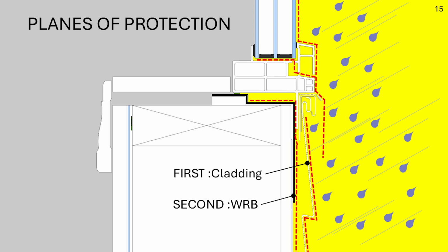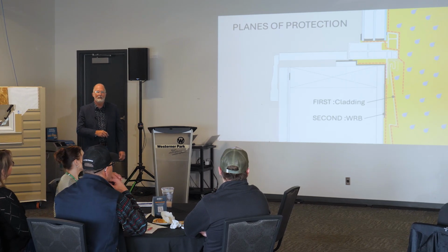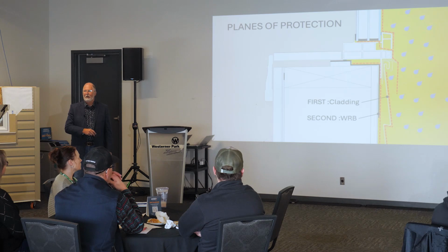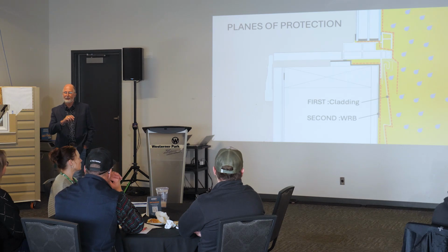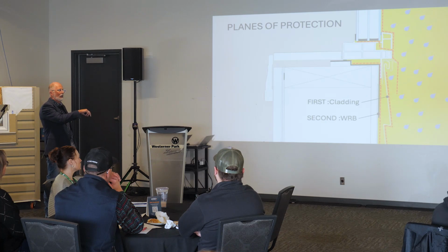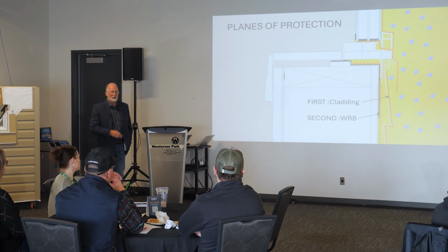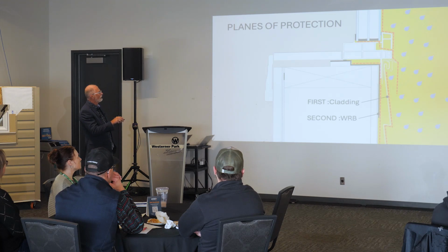This is exactly the same principle as that car door we looked at, right? There's the inside of the car door seal. There's the flange. Why do you need to seal the flange? You don't really if you have everything else done correctly. And if you give the water a place to go, it'll go there. And then because there's no air pressure difference, gravity will simply pull it back out and it'll dry that space. So you notice where that joint is, right? It's on the window itself.